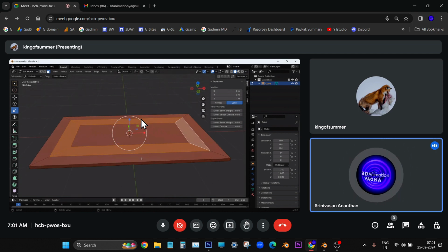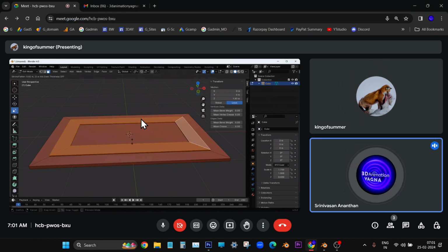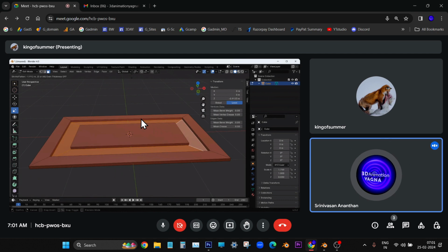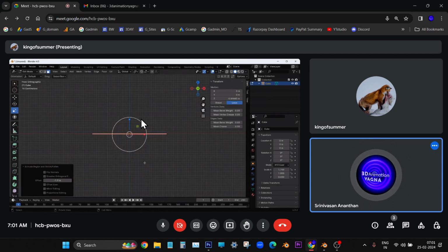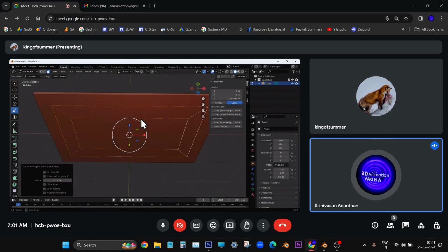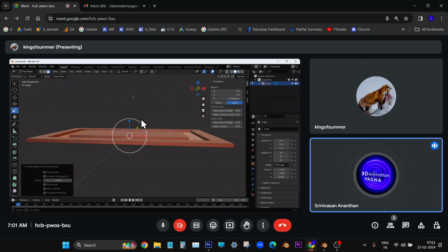Now press Alt E and choose second option, and now it will ask you to move it downwards, move it slowly downwards, just above, enough, leave it. Yeah. Now just go to front view. We are able to see in the bottom. Go and see the bottom. Just turn the camera and see the bottom. We are able to see the lines, which means mesh intersection is happening.